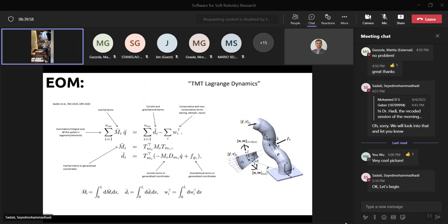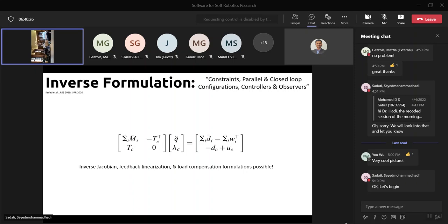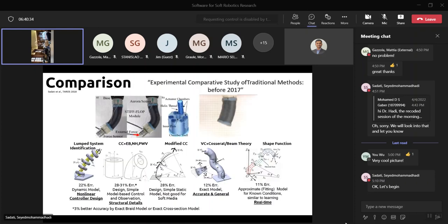I improved that for the case of differential kinematics, and the beauty was you end up with a summation. So basically, for the different elements you generate the derivations separately, and you just concatenate them in your final script. You don't end up with a large Lagrangian that you have to do partial differentiation on for the whole system, with ugly equations. The inverse problem is easier than in any other rigid body dynamic case that you've already seen.